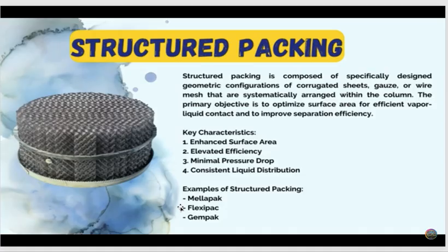Here the shape of structured packing, and we have to consider that it enhances the surface area, elevates the efficiency, gives minimal pressure drop, and consistent liquid distribution. Examples: Mellapak, Flexipac and Gempak. These are the structured packing. Okay, you have to know when to choose the structured packing.